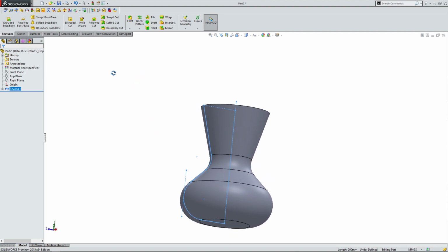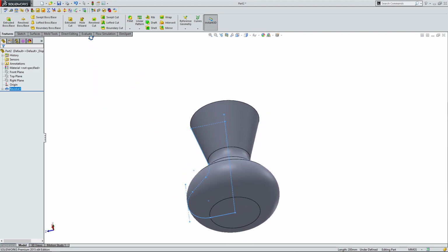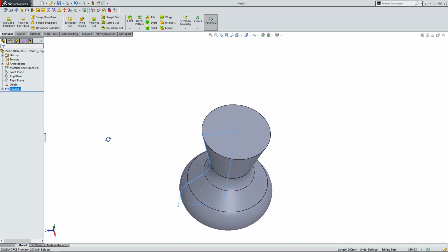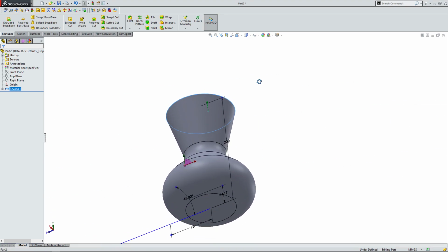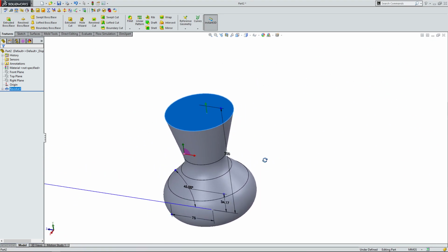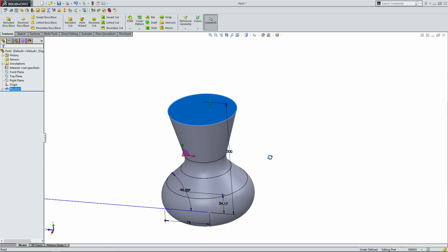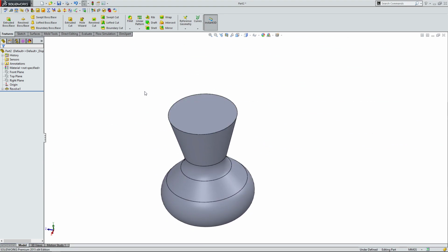So now that we have our design, the next step would of course be to allow us to fill it with liquid. In this case, it's really just one solid shape, so something is going to need to change to allow us to do that. And so for this example, we're going to use shell, and that's a command and a feature that we haven't spoken about yet, but it's really simple to use, and it's very effective, and it will make your life a lot easier.